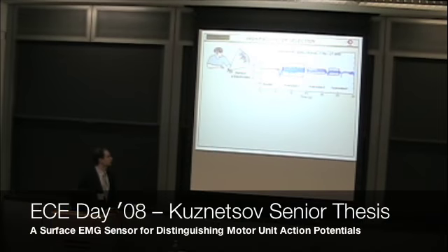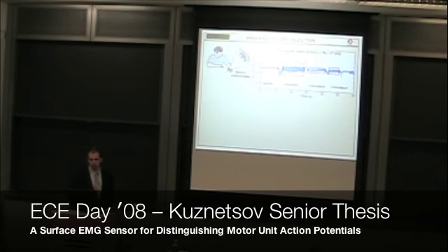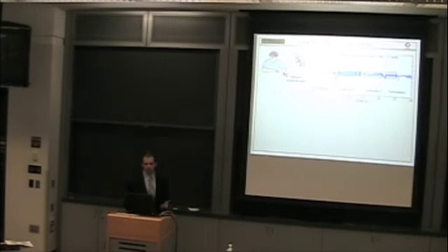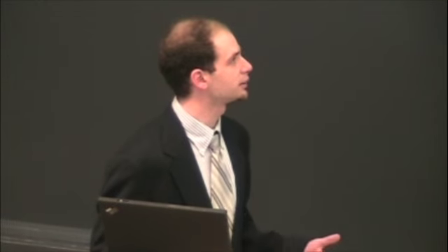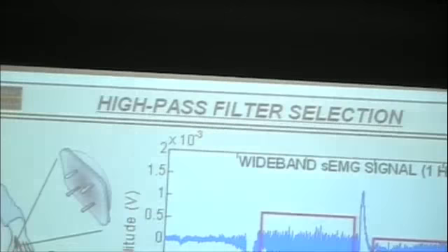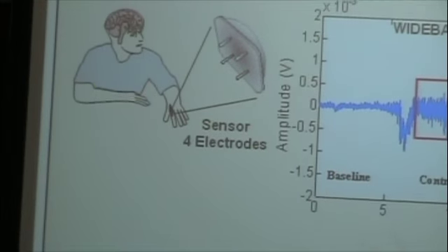The time domain representation of the signal appears in the upper right. In this representation, we see that the signal consists of areas of relatively stable electrical activity of the sEMG signal that comes from the muscle, that are interrupted by these large offsets. And these pulses, these offsets, are due to movement artifact. We would like to remove them as best as possible and preserve the baseline and contraction.